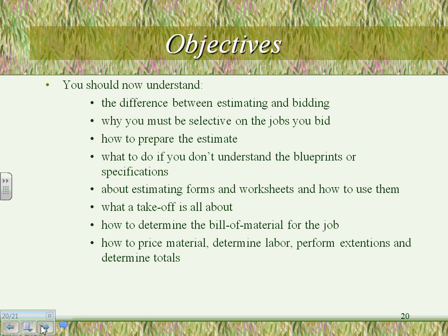This one is not as good, since you take the switch separate from the box and the cover. They go in this sheet, guys, and they assign a cover and a box for each one of them. So if you look at the lay-in fluorescent fixture, the quantity is 8. I need 4x4 boxes to tie them, 9 boxes. EMT, I have the mud rings for them.